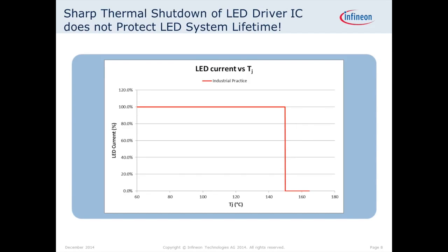There are some LED driver ICs in the market which claim to have thermal protection, which is true, I guess, but this thermal protection is only related to the IC itself. As you can see in this chart, as I've shown before, the LED lifetime goes down already much earlier than when the thermal protection of the IC kicks in.